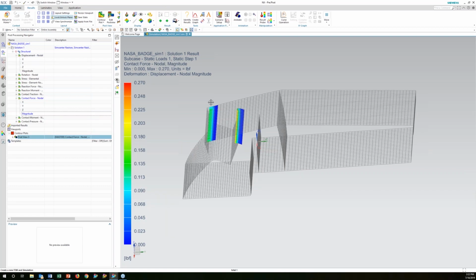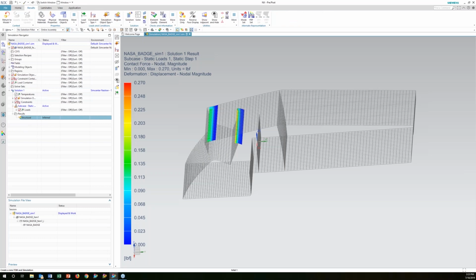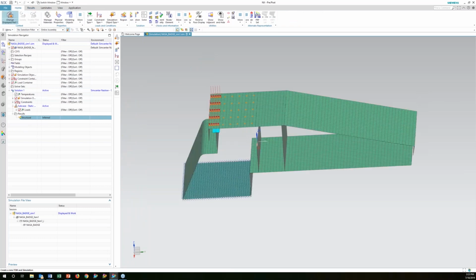But what I like to do anytime I'm doing nonlinear analysis, hey, let's get it to work in a linear realm first before I go ahead and step up to including large displacements and including material nonlinearity or geometry nonlinearity. So that's where we're going to go next. Let's go ahead and make sure that we can get 402 to work before we turn on large displacements.